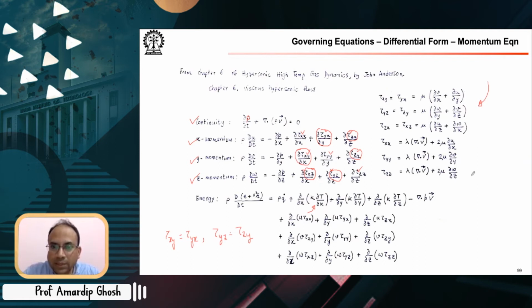these elements. Once again, this is something that I wrote on the previous page. These are the shear stresses, and these are the normal stresses due to viscosity. And you see that the normal stresses have a form that is quite different from the shear stresses. So the normal stress tau xx is a compressive or expansive stress, a normal stress on the x plane.